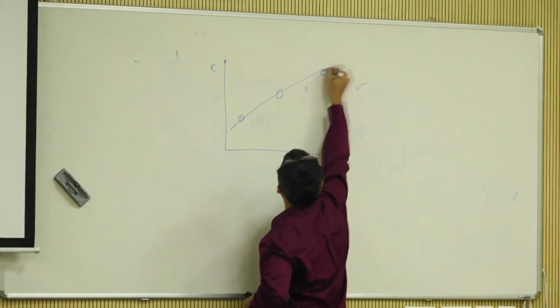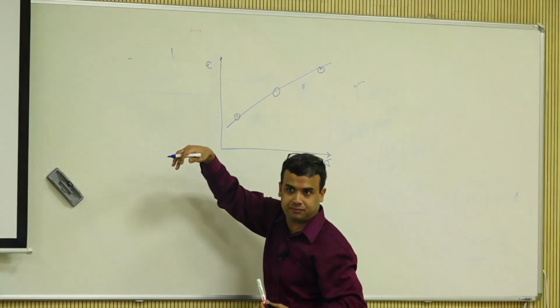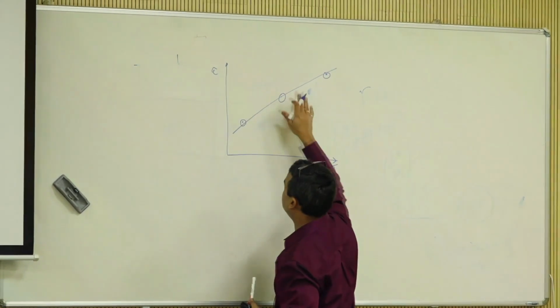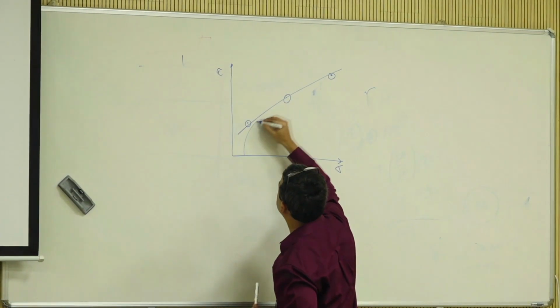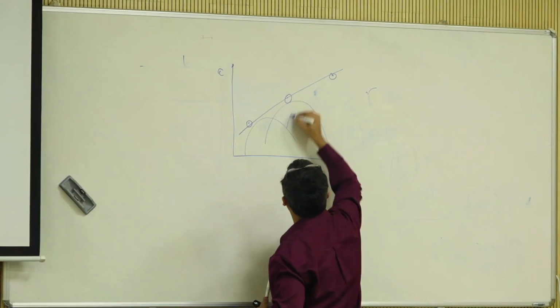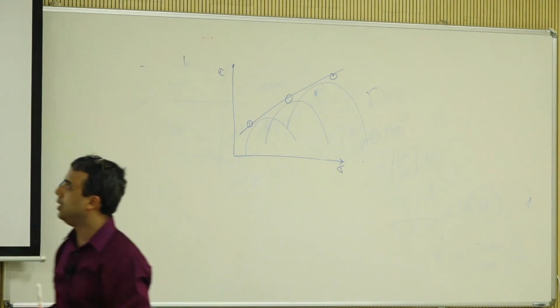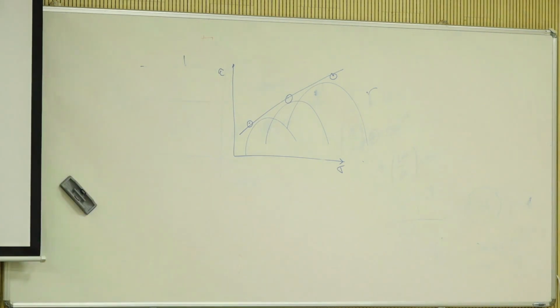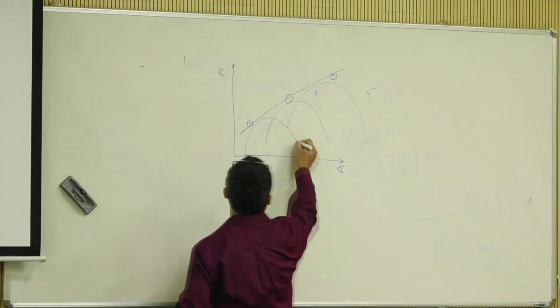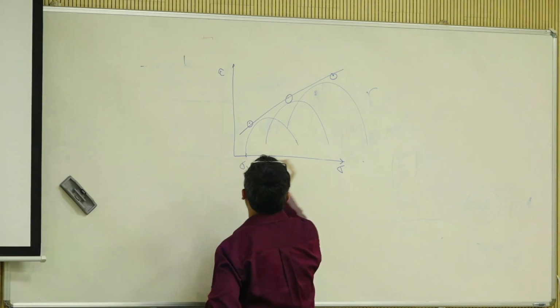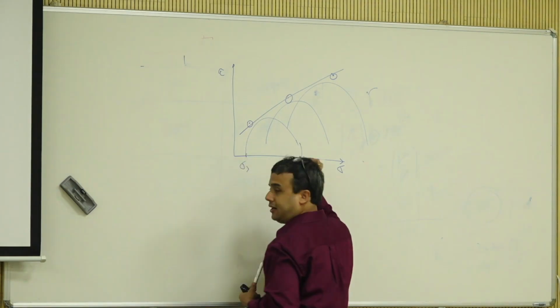You join that, that's your C versus P, C P. Whereas for triaxial, you have to draw more circles and you have to draw the tangent and stuff, and then you go. The point is, when you draw sigma 3 and sigma 1, every triaxial test has a combination of a sigma 3 and a sigma 1, right?